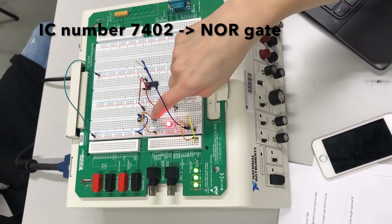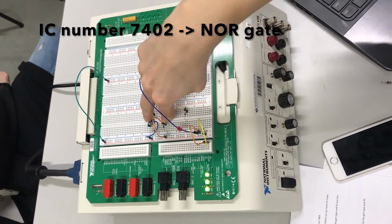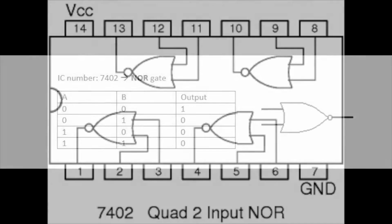The last IC was number 7402. We only got positive output when both inputs were false. From the table, we can see that we have a NOR gate. A NOR gate is an OR gate followed by an inverter. Its output is true if both inputs are false, otherwise the output is false.